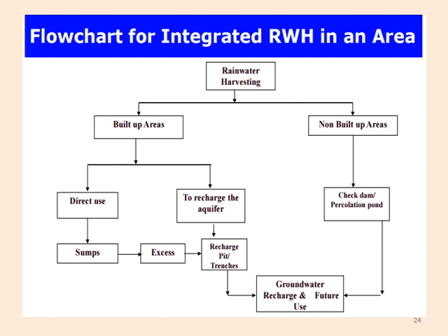For built up areas, it can be done by direct use or to recharge the aquifer. For direct use, sumps or wells are used for storing the water, and the excess water can be conveyed to a recharge pit or trench to recharge the aquifer. Like this, groundwater recharge can be done.